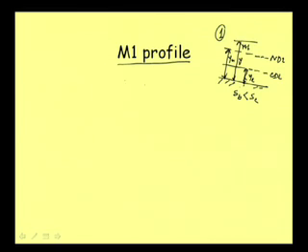So, what we are getting is that y is greater than yn and yn is greater than yc. So, this is the very basic relationship between depth of flow profile, that is, depth of gradually varied flow profile, the uniform flow depth and the critical flow depth.